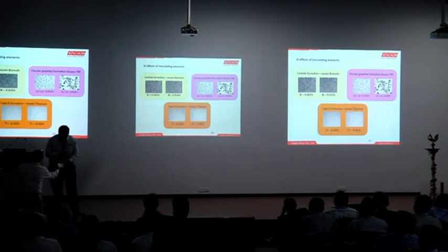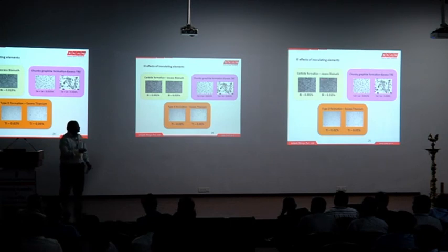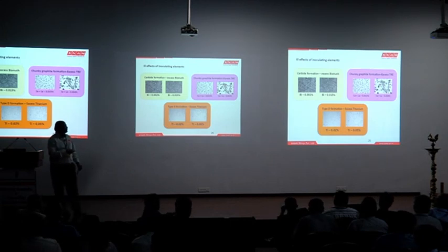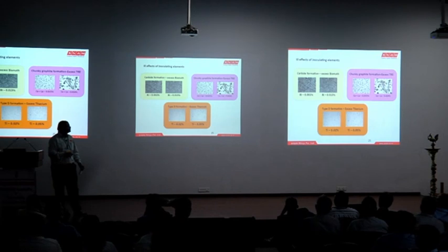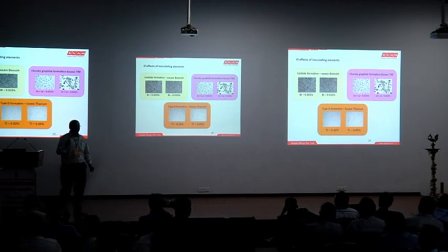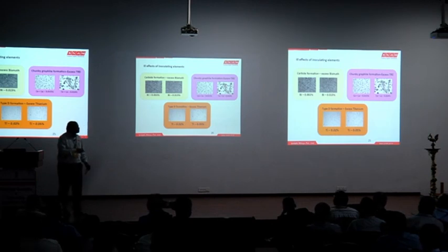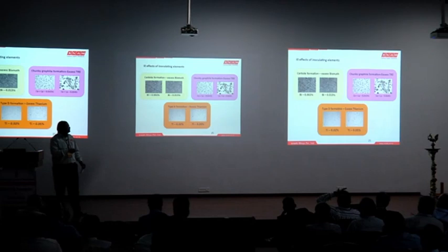These are the ill effects of, I've come to the last slide, these are the ill effects of inoculating elements. What happens when you overdo your inoculation? It's overdosing. Too many sleeping pills will take you to the forever sleep stage. So excess of cerium and lanthanum, excess of bismuth, excess of titanium, these are the ill effects of its own, the individual elements' characteristics.